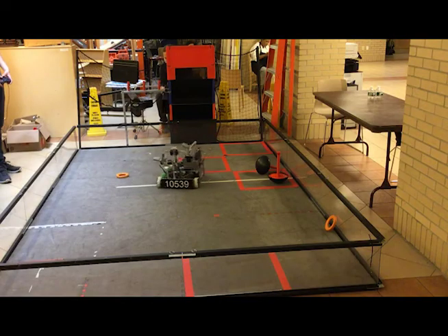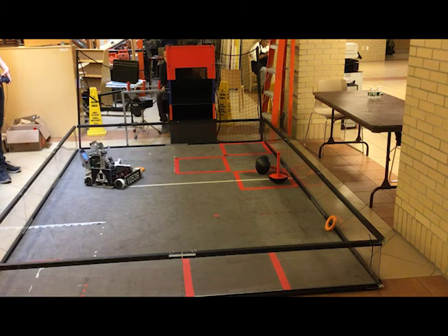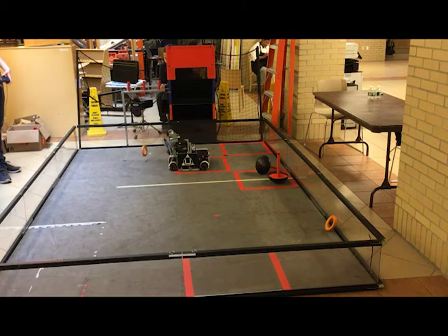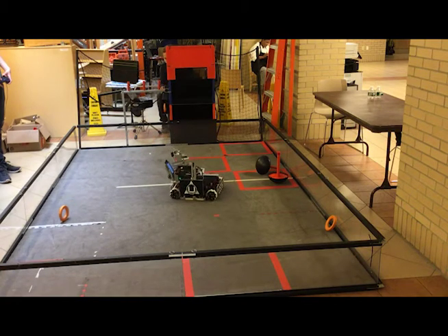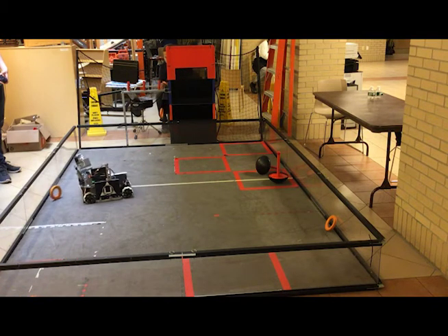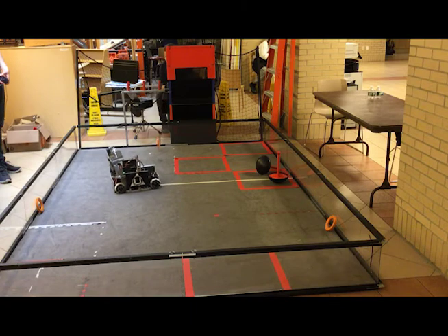Our drivers also have the ability to adjust which side of the robot is the front of our robot. This is important because we want to make sure that our drivers, some of which have different preferences than others, feel as comfortable and as efficient as possible when controlling the robot. If the left bumper on the first gamepad is pressed, the side of the robot becomes the front of the robot. If the right bumper on the first gamepad is pressed, the front of the robot becomes the front of the robot once again.